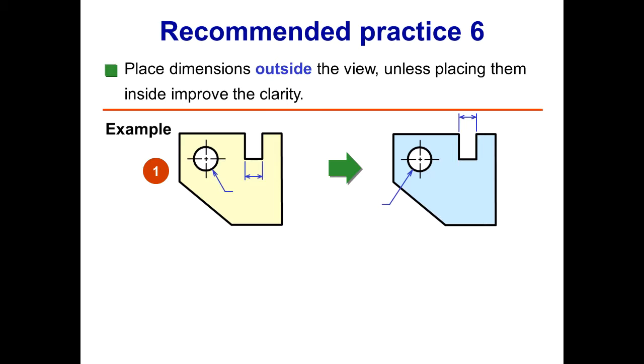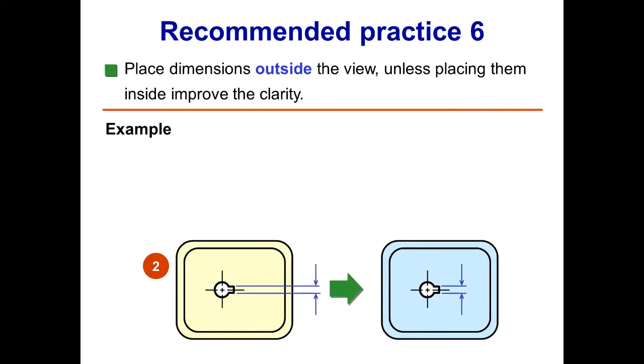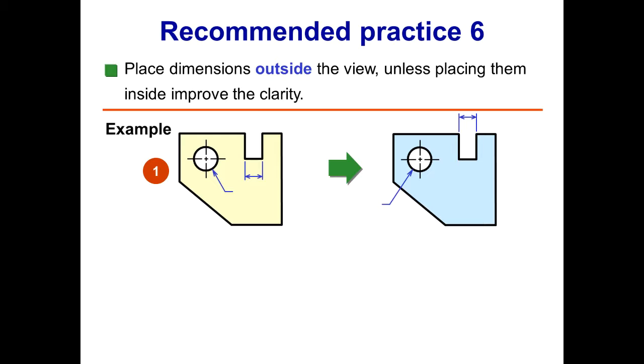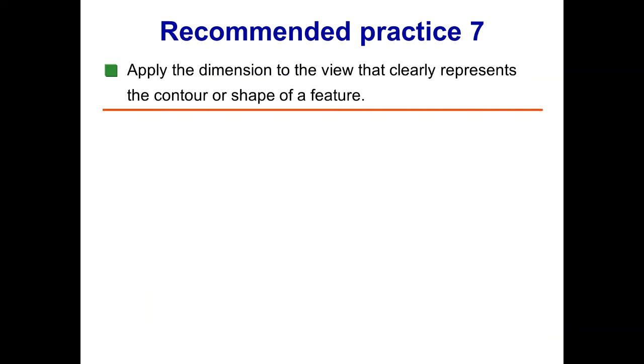You need to always try to place the dimensions outside the view unless आपकी जो dimensioning है वो अंदर करने से view की थोड़ी सी clarity में increase हो रहा हो, then you can place the dimensions inside like this, but most of the time it's recommended that you put the dimensions outside of the view. Apply the dimensions to the view that clearly represents the contour or the shape of the feature.